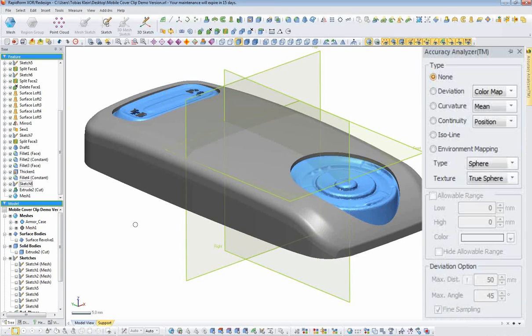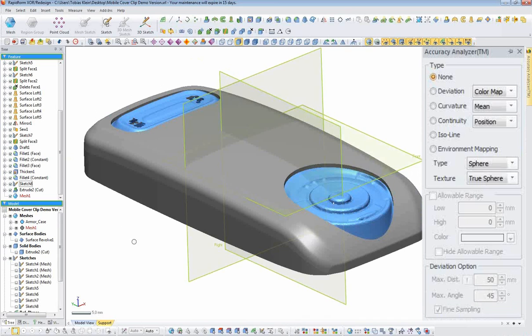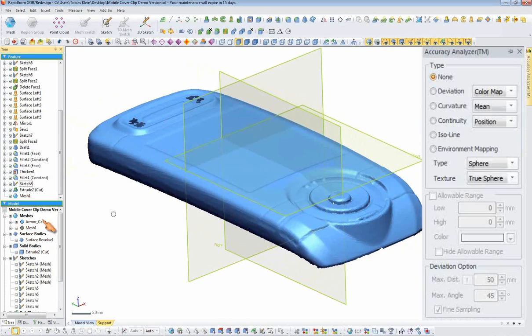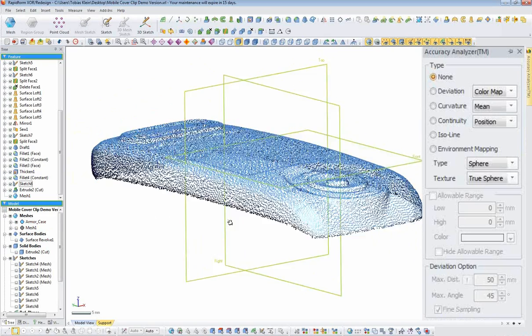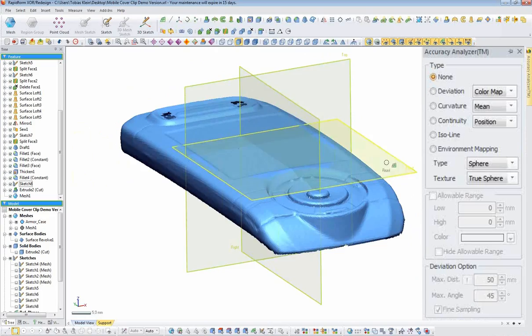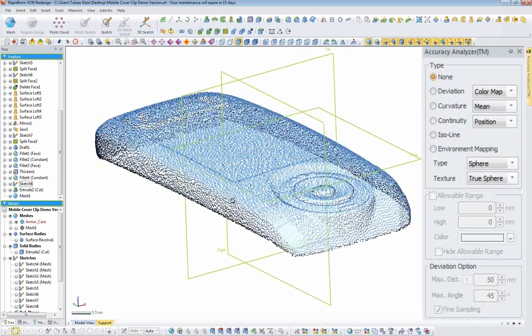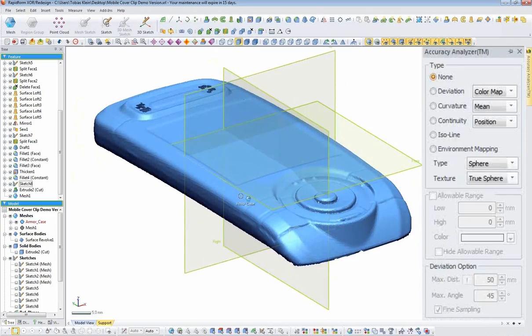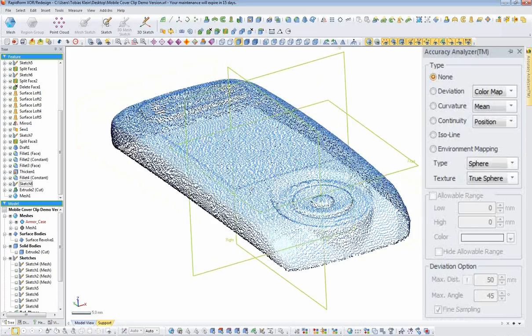Okay, there is a question about automatic surface creation from scan. Automatic surface creation is of course possible. If you want to create a surface automatically, this surface is not a CAD surface. This surface is just an as-built surface, which is basically converting the mesh into a surface.